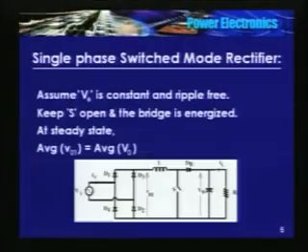Let us see how it works. A simple full bridge diode rectifier. I use an inductor L, and a switch here, a diode, and this is the output stage, a capacitor, and I connected a resistor here. Let me tell you one thing, I don't need to connect a resistor here. You can connect some other load to these terminals. What sort of a load we will see sometime later. As of now I connected a resistor.